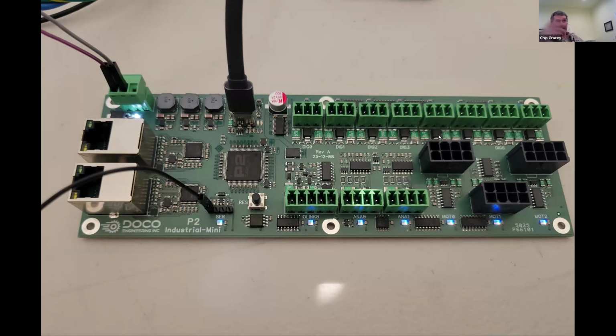You can string those things together just like a SPI bus, and send data out there. You set your data up, clock it, catch the data coming in from the other side, and then just repeat that. Then when you're all done, you hit a latch signal, and it updates everything at once. It captures new data into the 165s and then promotes the internal shift register in the 594s to its outputs. So I wanted one cog to be able to handle all that stuff and the LEDs and this H-bridge chip. But it became really challenging and took me a lot more time than I thought it would.